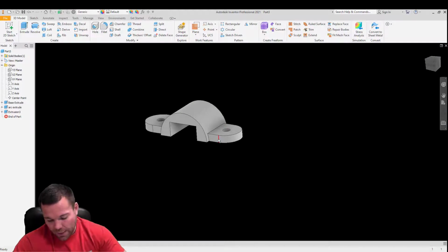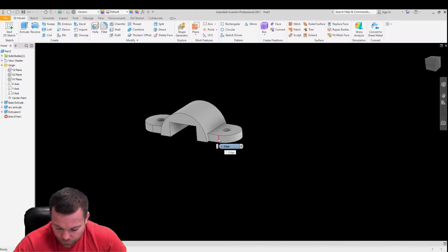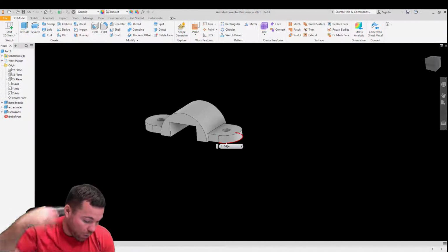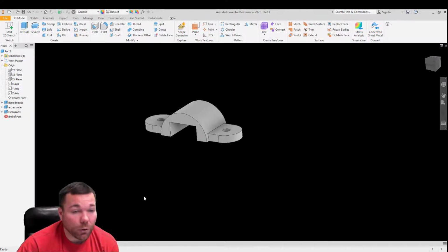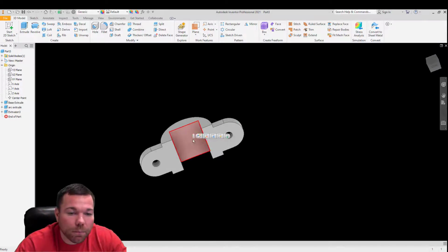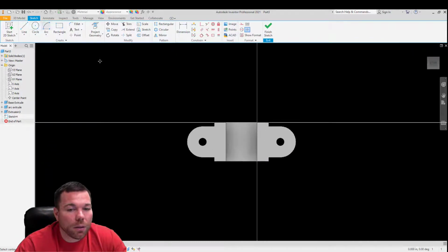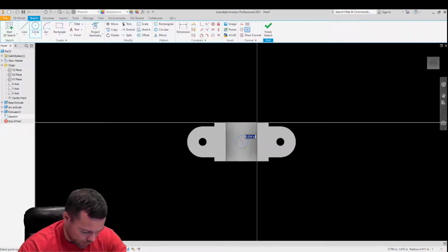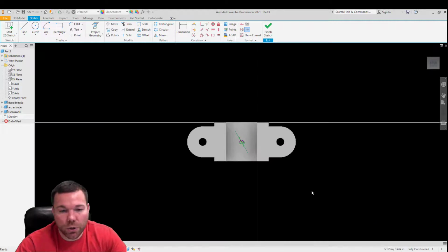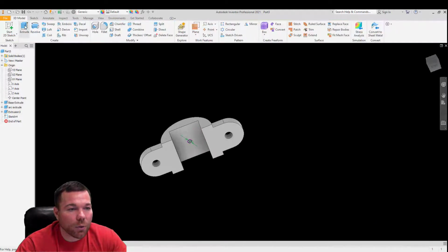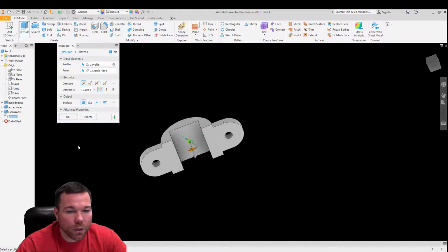Now, of course, that has a rectangular extrude in there. And let's see here. So next we are going to add a hole into this. So it appears we're just going to click on the bottom. And we're going to add a hole right there. And that is actually constrained to the center point. And what size hole is that? 0.25. And you can see it's fully constrained. So I'm going to finish that, and we're going to extrude that up through, full cut.